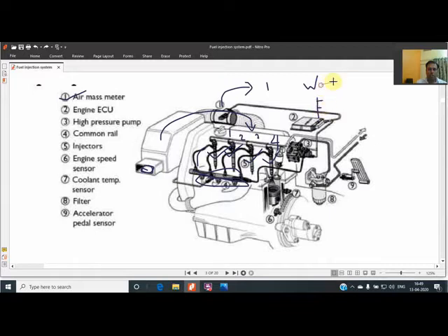The basic difference is one is giving the electrical signal and another is giving the data signal, because these days most of the vehicles are working on ECU system, so the hot wire has somehow become obsolete and now the hot film air mass meters are used, for measuring the quantity of air which is flowing. Different types of air mass meter are used.